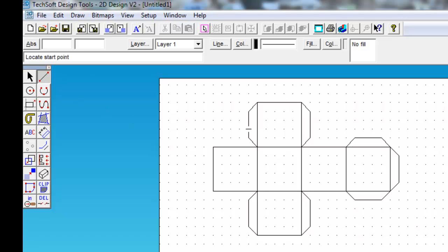For laser cutting, obviously you want some of these lines to be cut, and then some of these lines to be scored or engraved on the machine so it doesn't cut all the way through. This should make folding the net easier. So you have to tell the laser cutter which lines are cutting and which lines are for scoring. Laser cutters generally work using color coding of lines.